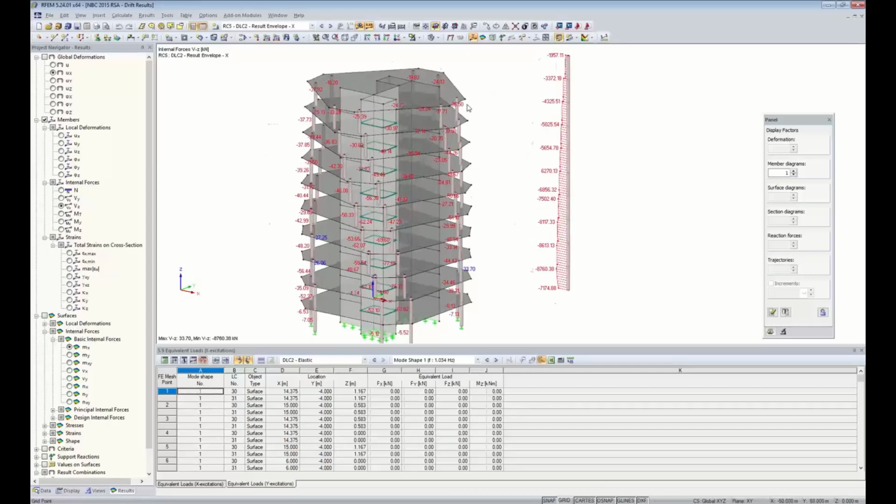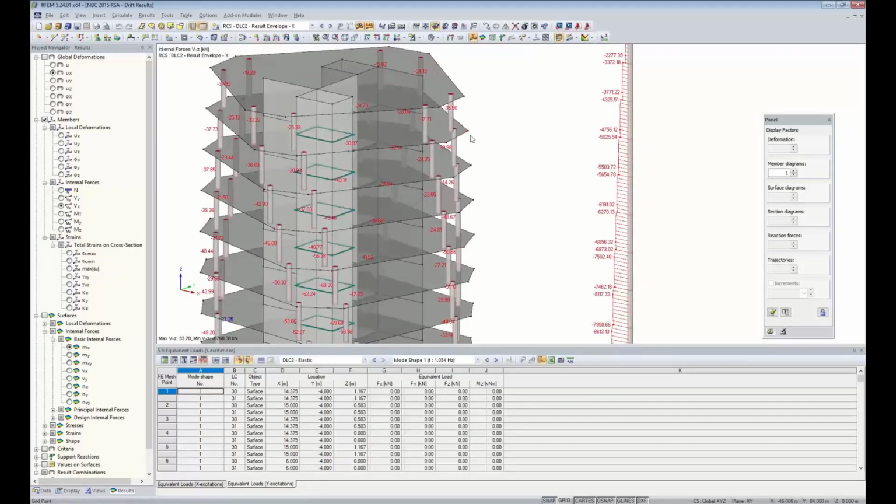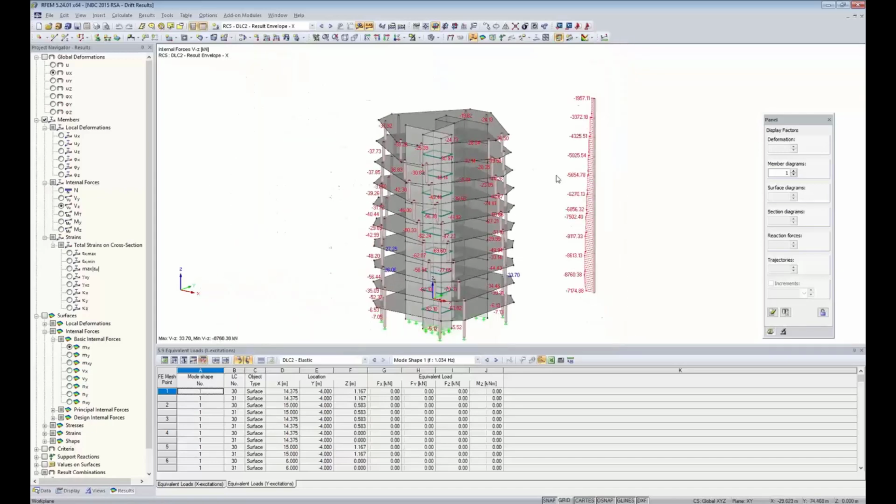For our case today, the inner story height between our levels is 3.5 meters. So 3.5 meters times, let's say, 0.02 directly from the standard gives us a limiting inner story drift of 70 millimeters. So how can we tell the drift here for each one of these stories?